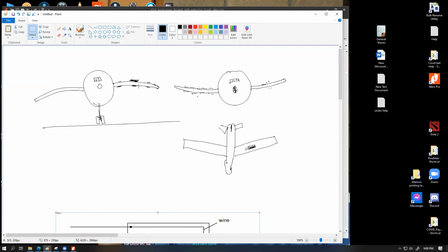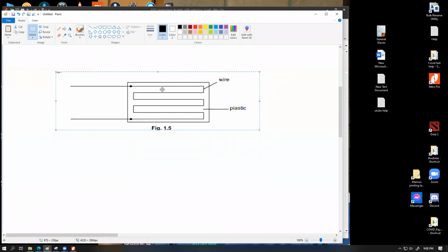Might as well be 1 foot long, but they are significantly smaller than the length of the wing. So if we have a lot of wires undergoing the same amount of length increase, then measuring the variation of the length is easier. So let's say one of these wires actually increases by 0.1 millimeter, and if you have tens of these wires, in total this 0.1 millimeter length increase gives you a certain rise of resistance, which we're going to measure by applying some voltage across these 2 points.